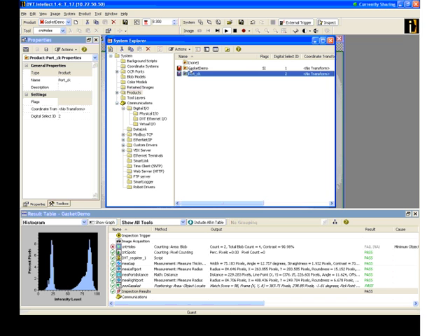Right now I only have 2 products in here. One is called the gasket demo, the other one is port check, which happens to be product select ID 2. So in order to select this, I would have to make bit 1 go high and bit 0 be low, and select this product. So let's go ahead and take a look at how to do that.